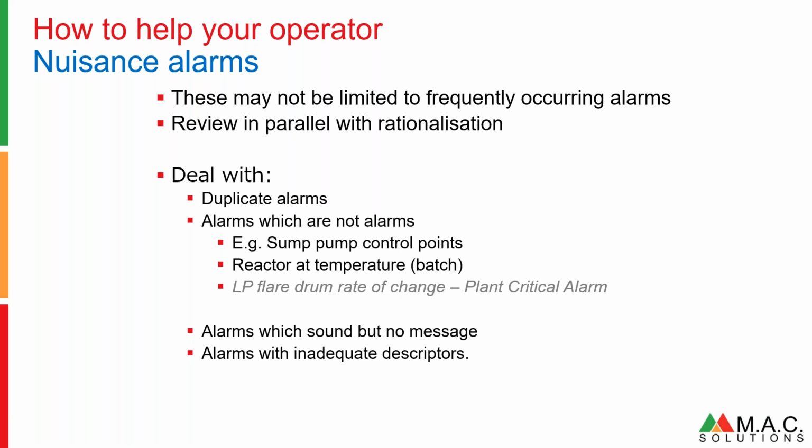Think about when you're rationalizing alarms that sound but have no message. About 8 years ago, I did some work on a different batch plant to the one I worked on recently, and they had alarms. When I went to create some new software, because I also did software, the operator said, "I hope you're going to sort this out better than the current system." I said, "Why?" "Well, we've got alarms that we don't know what they are." Pardon? Alarms would be generated, a sounder would annunciate, and no message appeared on the screen. When the software had been previously configured, they'd forgotten to put alarm messages in with a couple of alarms.